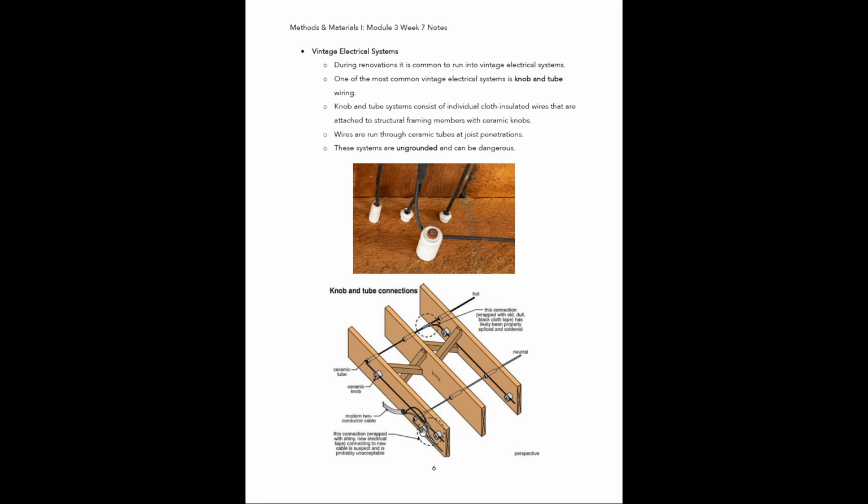So that's what you're seeing here. And that's a nightmare for a home inspector. That's a big no-no, and that's something that they're going to flag because that's a bad thing to do. My house definitely had some of that. It's just common to see, throughout the years as people are doing renovation projects. Maybe they didn't want to pay for an electrician, or they wanted to cut corners and do it the easy way. So instead of redoing the entire thing, they'll just tie the new stuff into the old stuff and just electrical tape it together.